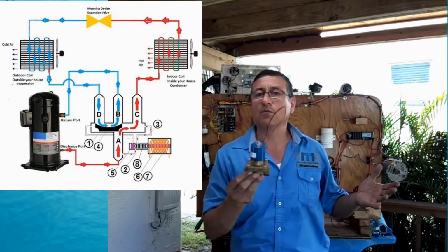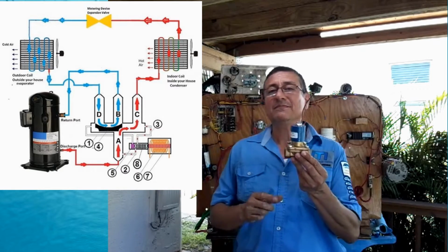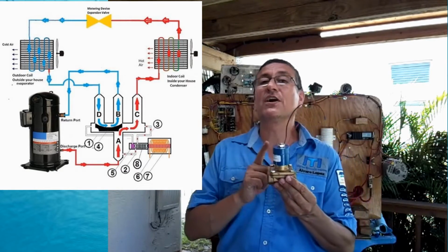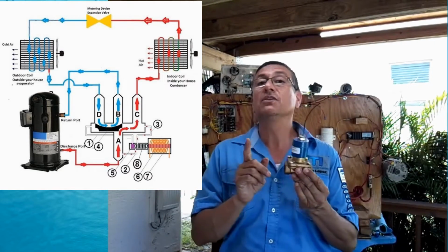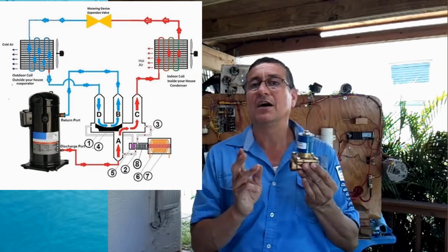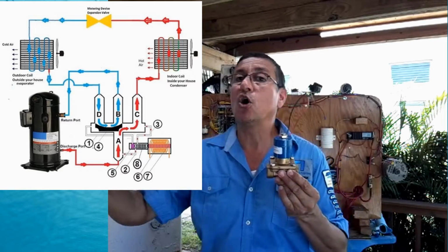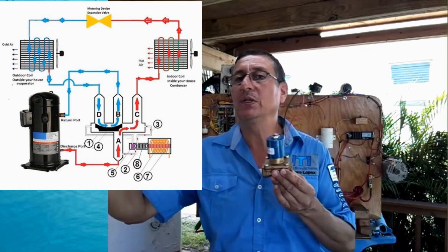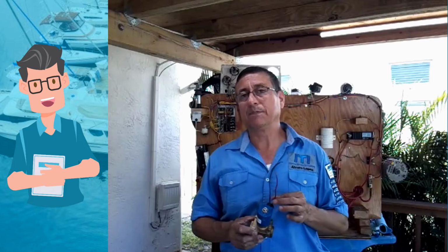In air conditioning systems, we use solenoid valves. In an air conditioning system, the solenoid valve is used to reverse the cycle from heating to cooling or cooling to heating. It's a solenoid valve, 3-way valves that control the flow of the refrigerant to the evaporator or to the compressor, heating or cooling. There are other applications that we are going to study in our class of auxiliary systems or in hydraulic systems, and also in our class of air conditioning.